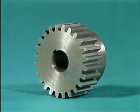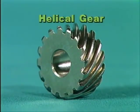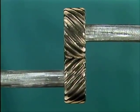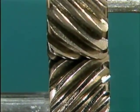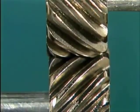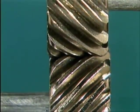As you recall, a spur gear has straight teeth. A spur gear that is made with twisted teeth is considered to be a whole new type of gear called a helical gear. As two helical gears mesh, the contact between the two gears begins at one end of a tooth and extends gradually across the width of the tooth. This allows the gears to run quieter and smoother. This is also true for the spiral bevel gear.